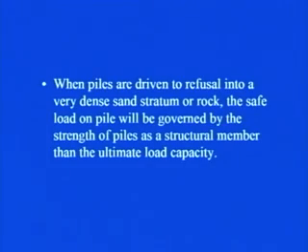When piles are driven to refusal into a very dense sand stratum or rock, the safe load on the pile will be governed by the strength of the pile as a structural member rather than the ultimate load capacity. See, from here you are finding out the ultimate load capacity, but the pile is made up of, let us say, steel or concrete.